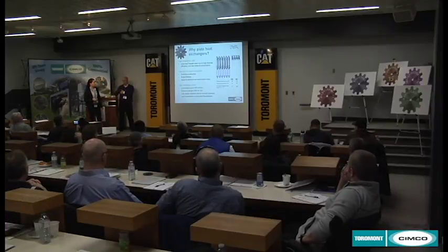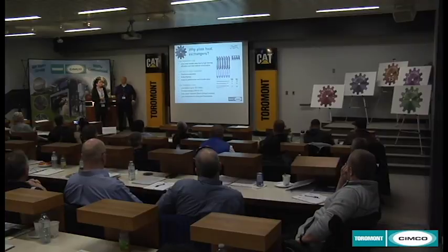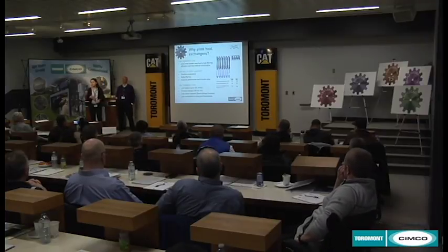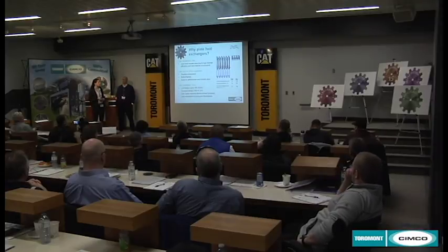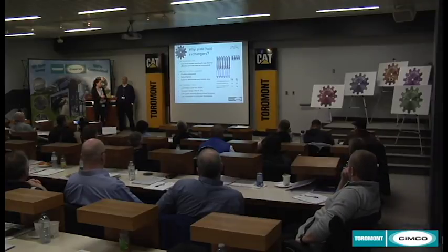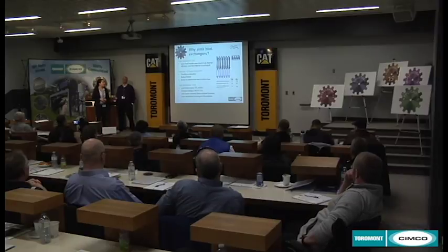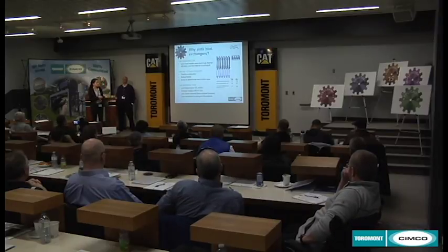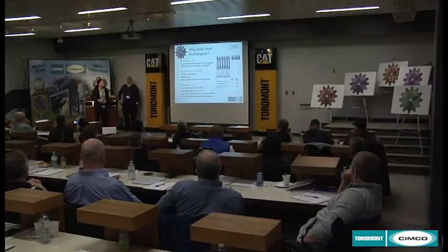So basically, the total weight operating tons on a plate heat exchanger will be 19 versus a shell and tube that it's 136. So floor area, installation, and maintenance will be between 14 to 21 versus 105 to 190.